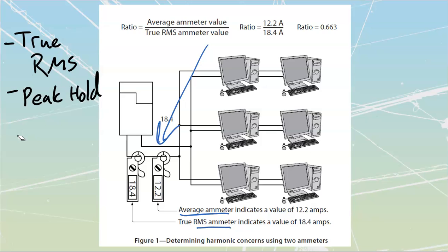Once again, working off that one line, if you have a balanced voltage at the source and then all of a sudden, 2 or 3 sub-distributions down, you're starting to see unbalance, it's going to be something on that system that's obviously causing that imbalance. You want to keep everything up to about 1% for your voltage balance. Voltage should stay the same across all components. So it should be 120, maybe it might be 119, and then you might have another one that's 121 or something like that. That's fine, that's 1%. Current is going to be more unbalanced, and so we allow imbalances of up to about 10%.